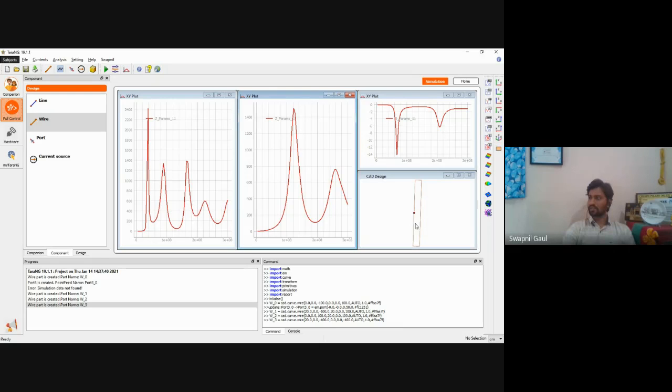Again, if you see this condition, we can also see that in the case of the folded dipole antenna, R in is greater than the radiation resistance, and the value of R in is very much. Because of that, we can compare P in and P rad, because P in is directly proportional to the square of R in, and P rad is directly proportional to the square of R rad. So here, if R in is more than R rad, P in will be more than P rad. That means whatever power we are feeding is much more than the radiated power, as compared to the dipole antenna. That means the efficiency of this particular antenna is going to reduce because P rad is less and P in is more.